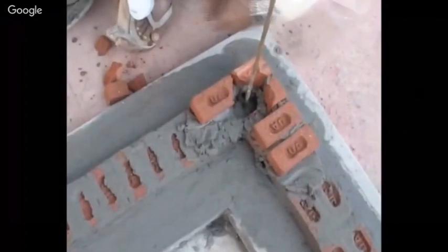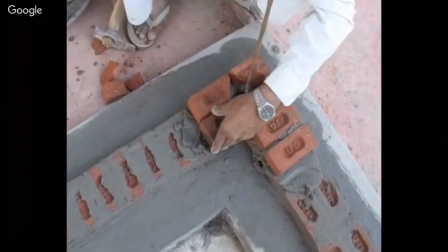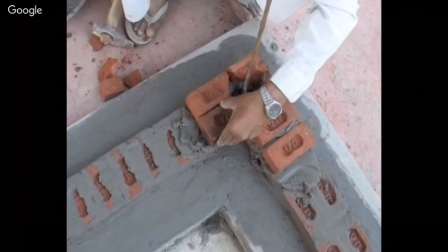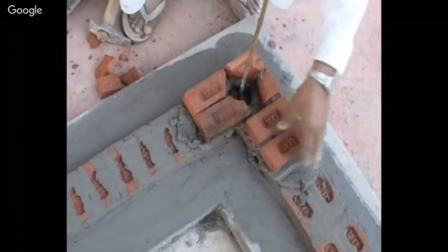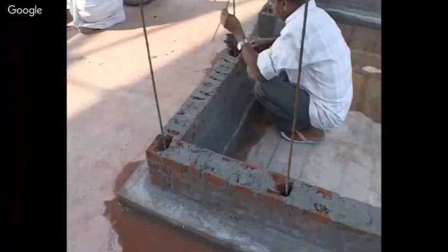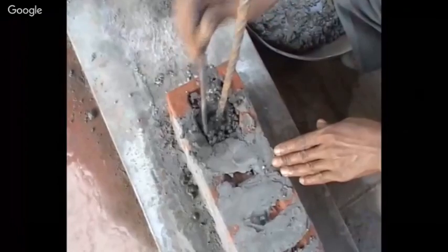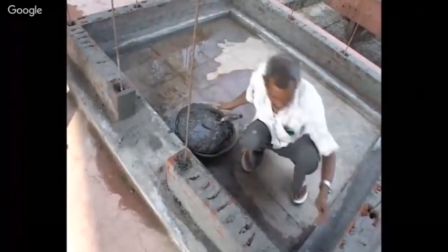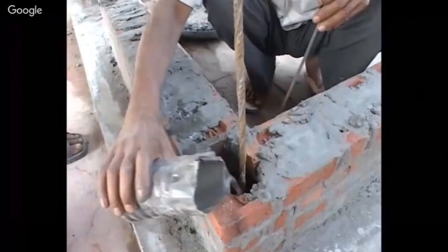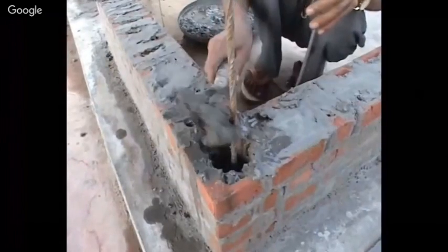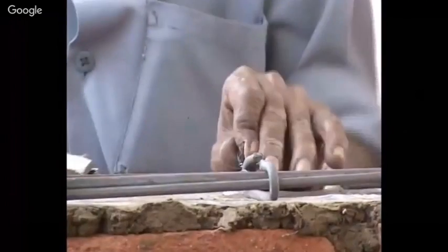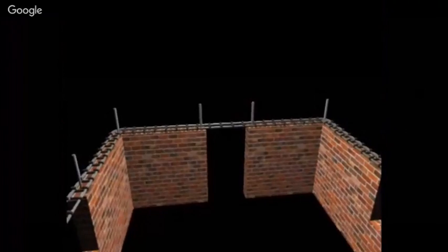As per chosen scale, half-size bricks are laid in 1:6 cement sand mortar, providing space for the vertical steel bars at the corners and near the openings. The gap along the vertical bars is filled in 1:2:4 concrete mix with 6 mm size aggregates after every 5 courses of the wall construction so as to develop full bonding. The walls are completed up to the lintel level and a monolithic horizontal seismic band is provided on all 4 walls so as to integrate the perpendicular walls.